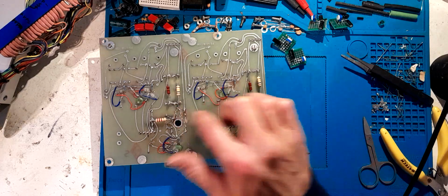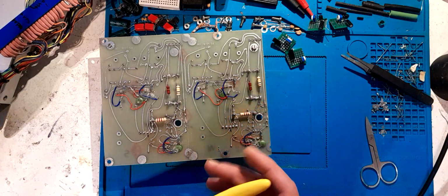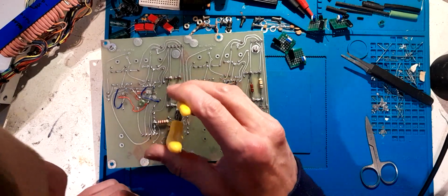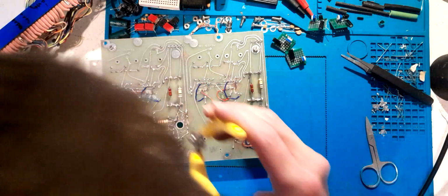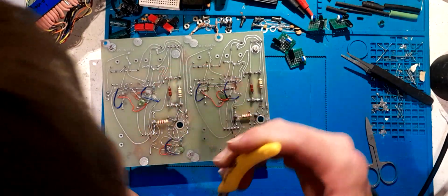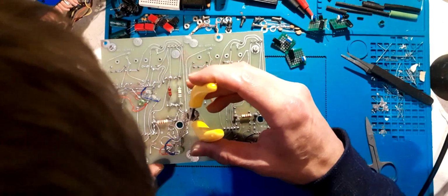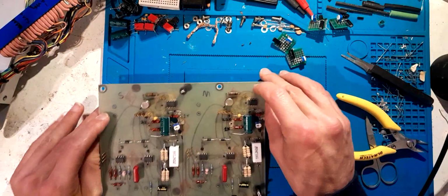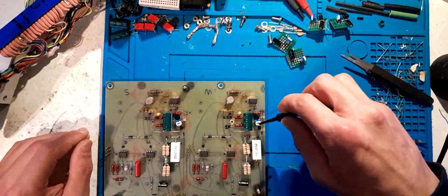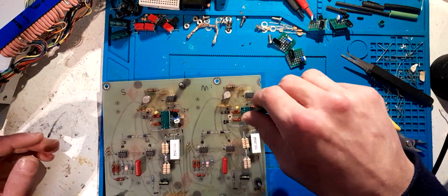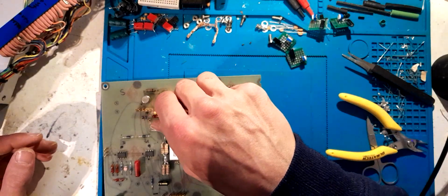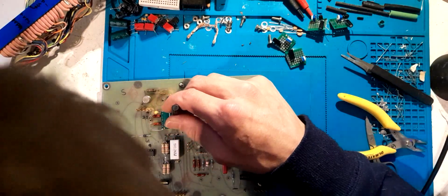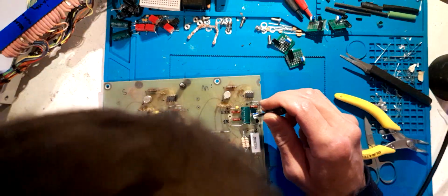But yeah, that's what I've done to get the TL431 integrated into the board. I'm happy with it. It might not be the neatest thing in the world, but I don't think it's the ugliest thing in the world either. It's all solid. It's a lot better than the way I had it, just flapping around in the breeze on the wires, so I'm happy with that. And the trim pots are facing up, so that's nice and easy to set them to whatever I want to set them to. That'll be about 10 volts in the middle, so I'll leave it there because I'll set this on my power supply.